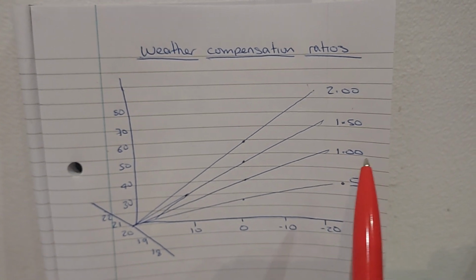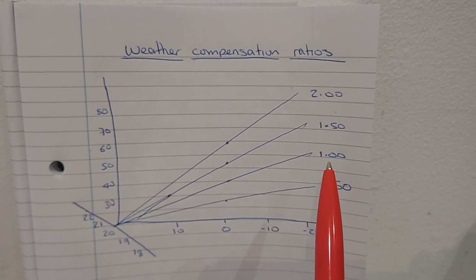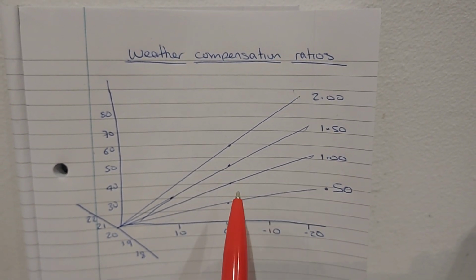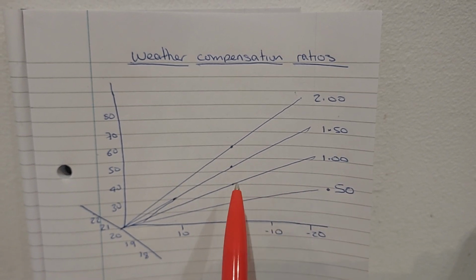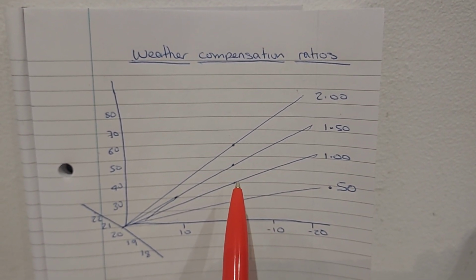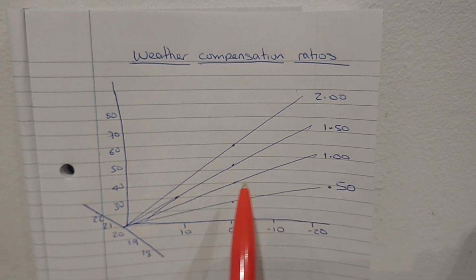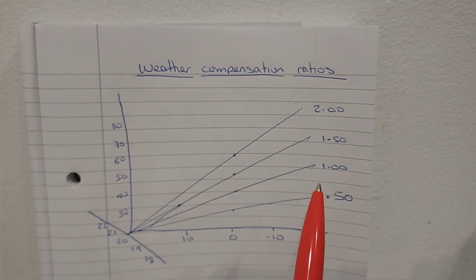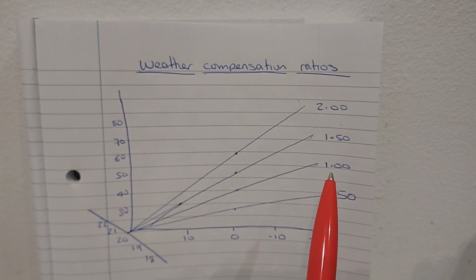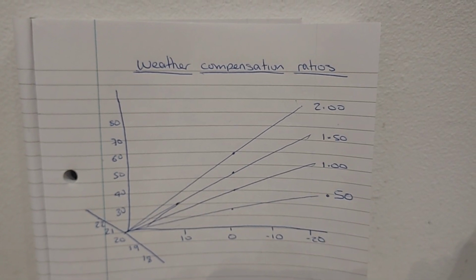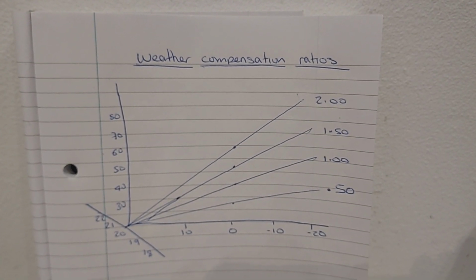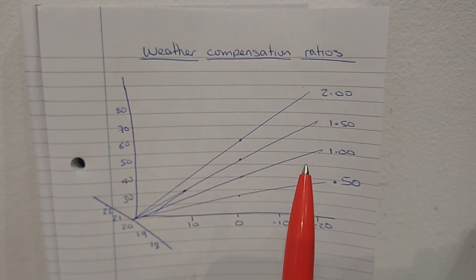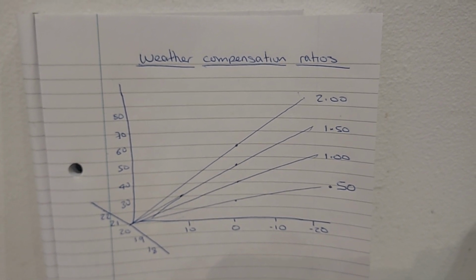So basically we're down into heat pump territory, underfloor heating territory with the radiators. And this might explain why we're getting people claiming that they're designing radiators and underfloor to run at the same temperature, and they're probably getting it on this ratio down here. Now I would argue that that's very good for radiators, very normal for radiators, but it's not that great for underfloor heating. So if I was going to install a system in a new build and someone told me to design the underfloor to the same temperature as radiators, I would ask the question, why did they want me to make such poor design criteria for my underfloor heating?